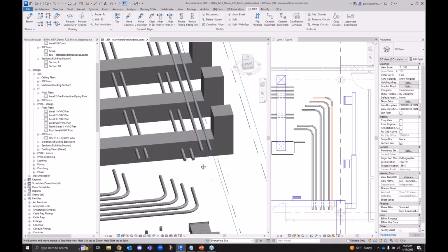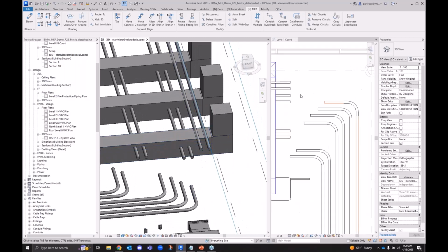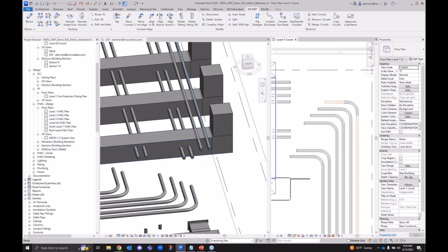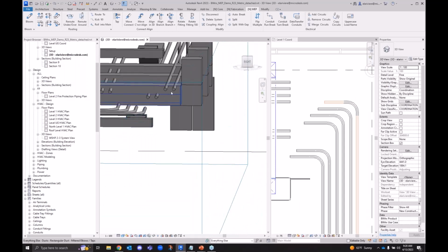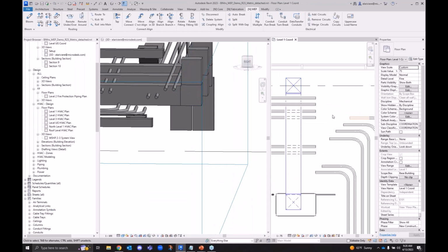So taking a look at those two upper elements here, right? We take a look at these guys. They're kind of far away. They're at an upper height, and that's going to be a really annoying connection to attempt to make. So let's go ahead and take a look at a command that would do that connection for us. We've got a really nifty command up here, route to.